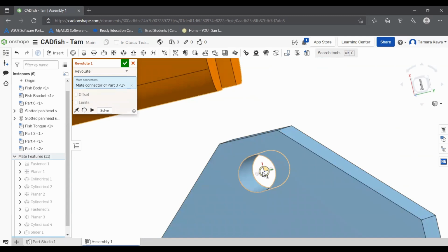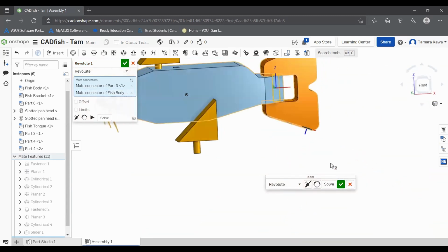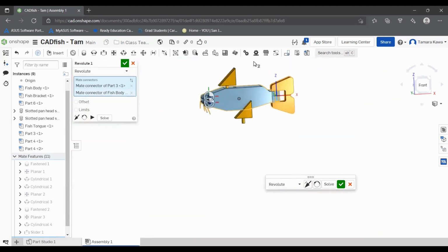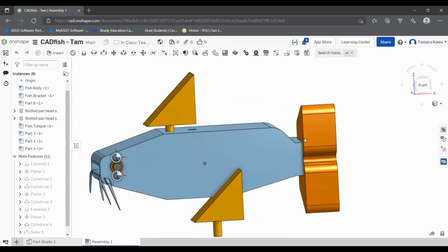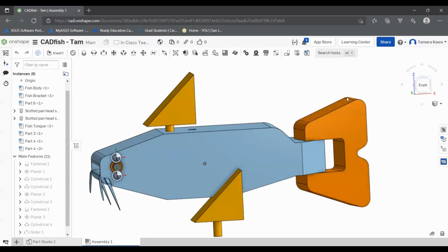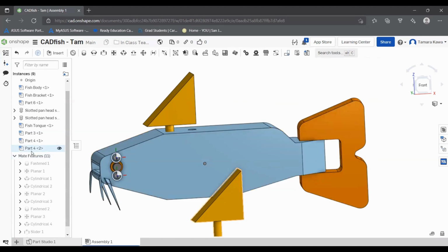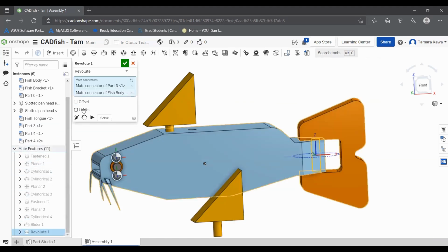All right. Catfishes are a labor of love, aren't they? All right, so now you should have this little fin sticking out of the back end of your fish. And you should be able to just sort of do what fin things do, but a little too much, or a lot too much, depending on your definition. And we can actually limit this. We can just right click on here and say edit, and we can add limits. So I'm going to add a limit of -30 and 30. So now if we animate that,